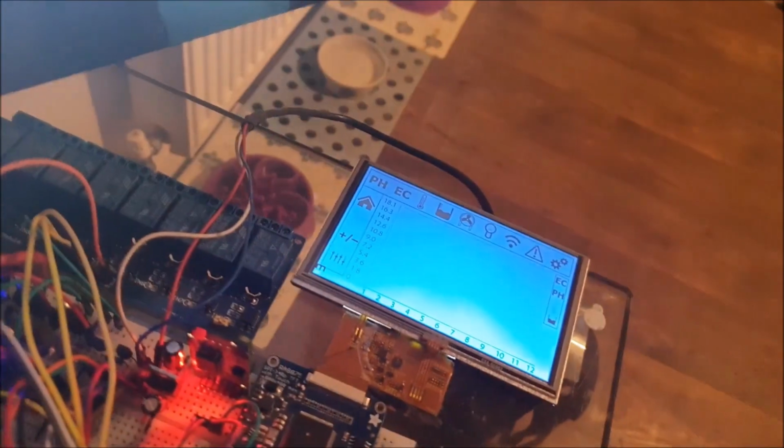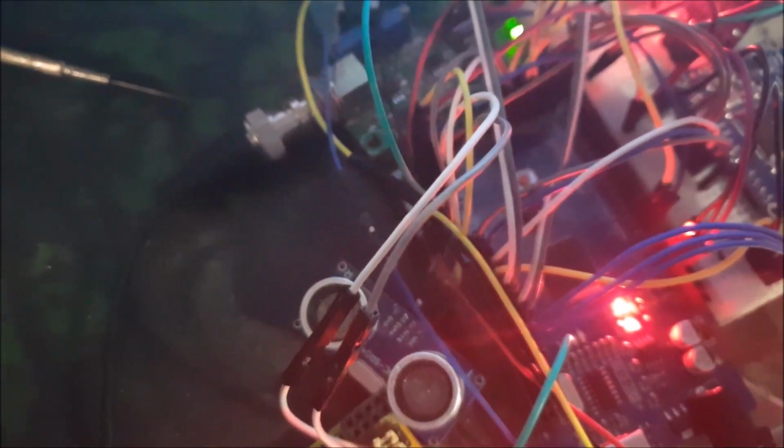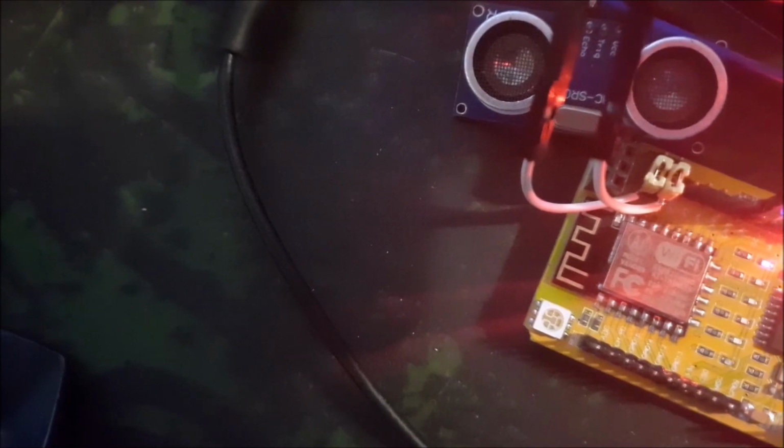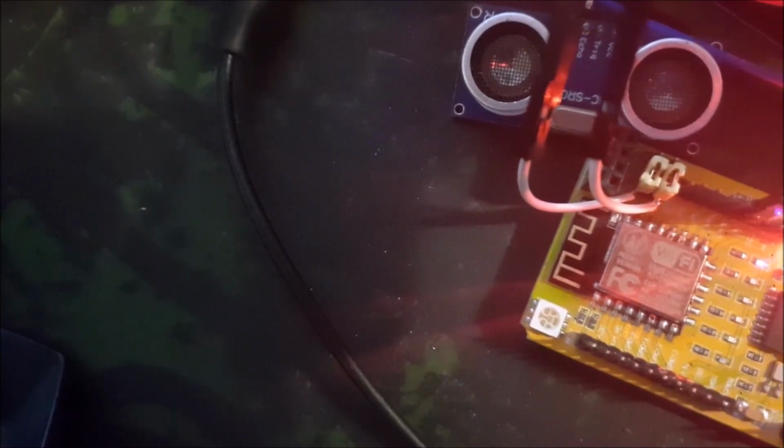Anyway, that's networking. I suppose I should explain how the networking works. It sends the data over one of the hardware serial lines to the ESP. This ESP chip actually didn't have the serial 0 pinned out, so I had to solder a couple of cables in there. But essentially it's just an ESP 12F or a 12E, but it's definitely an 8266 12E, sorry.